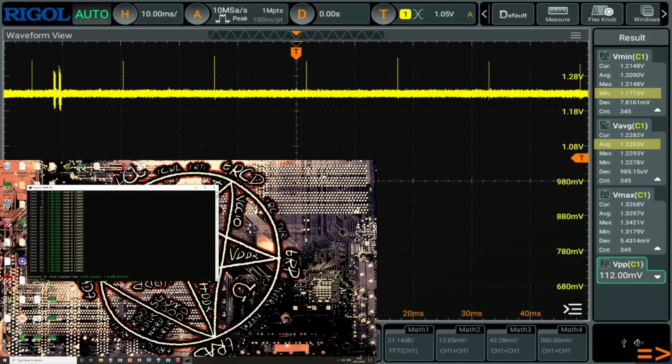Yes, it gets worse. Now we're seeing undershoot down into the 1.17 range, which is still not that bad, right? That's what, 60-ish millivolts? 50? Actually, more like 50, isn't it? Yeah, it's 50 to 60 millivolts. So quite an improvement, right? Mode 5 was hitting 1.13. We're now hitting 1.17. But I'm pretty sure we can do better.